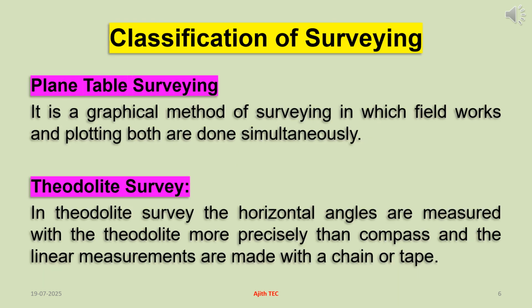Plane table surveying definition outlines the simultaneous observation and plotting of field conditions on paper by a surveyor. The plane table is a flat, leveled board mounted on a tripod that serves as the drawing surface. This eliminates the need for intermediate calculations and allows surveyors to visualize and map the area in real time. It is commonly used for small-scale surveys, topographical mapping, and situations where quick, approximate results are sufficient. This technique is simple, cost-effective, and useful in terrains where precision instruments might be challenging to use.